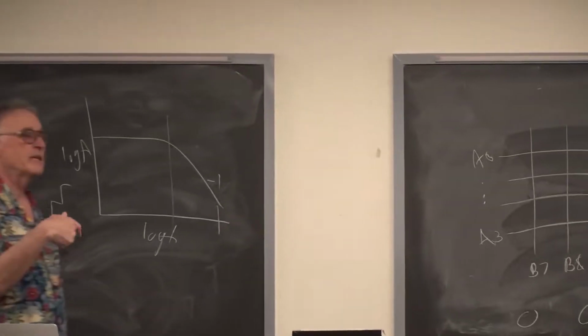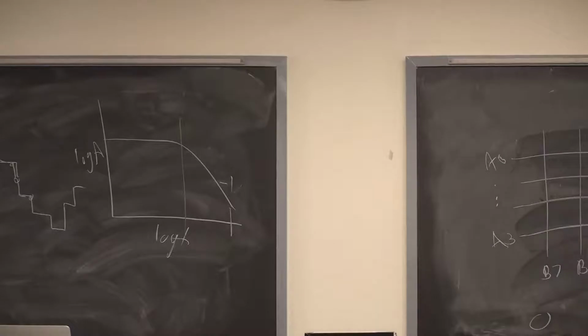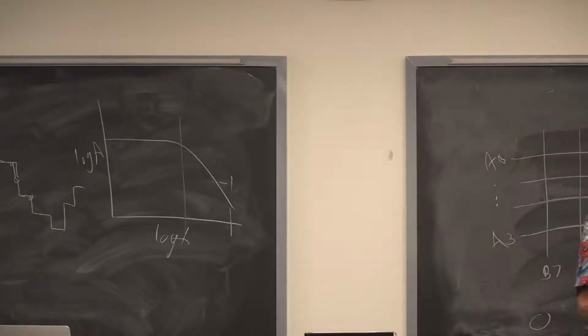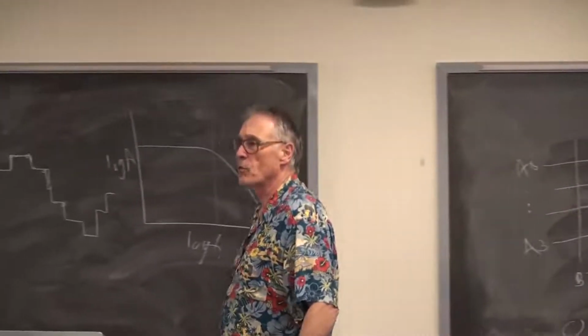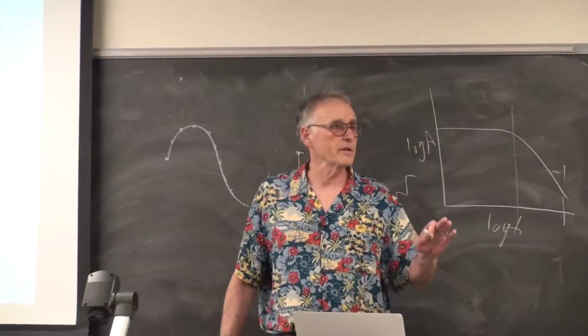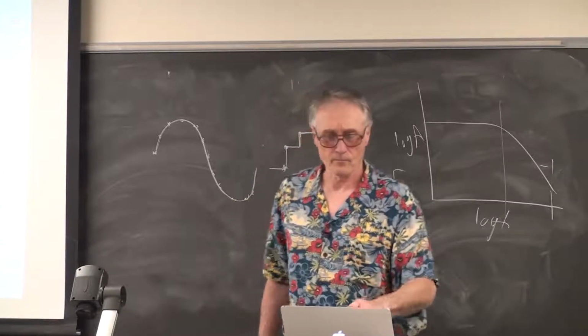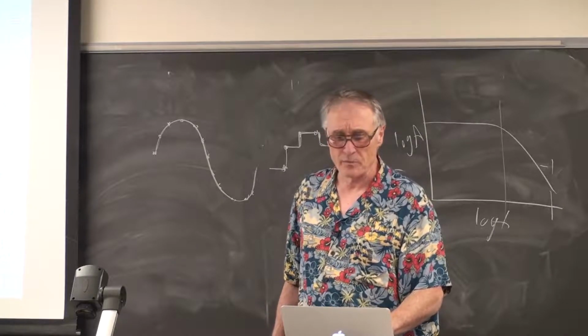That is because it takes the oscilloscope a second or two to acquire the FFT that you need to prove to the TAs that the frequency is correct and the harmonic distortion is low enough. So when you're demoing this to the TAs, you'll set it to 4 kilohertz or 6 kilohertz. You'll press the test button, and the TA will look for the spectrum equivalent to what was in the homework to make sure that the loudest component is an order of magnitude down from the fundamental. Frequency accuracy should be plus or minus 1%.